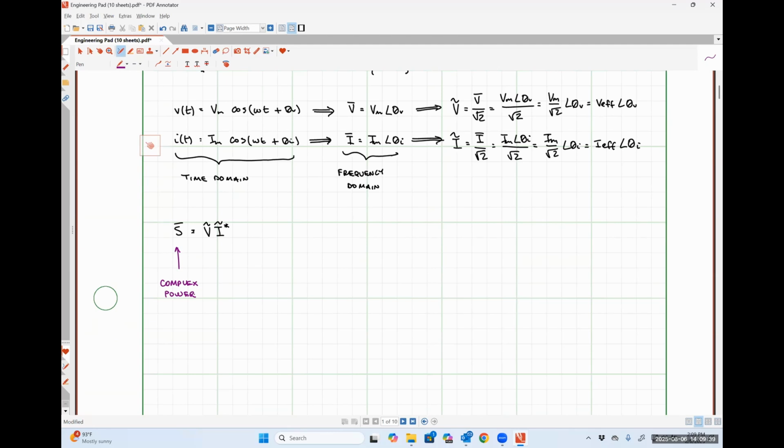Okay. So complex power is just an artificial construct that electrical engineers have created to describe what's going on in a steady state sinusoidal system. It is inherently a complex number, and buried inside of the multiple different forms of complex numbers, specifically the rectangular form and the polar form of a complex number, is really all of the different pieces of information that we could ever need to know about how things are behaving in a sinusoidally oscillating system.